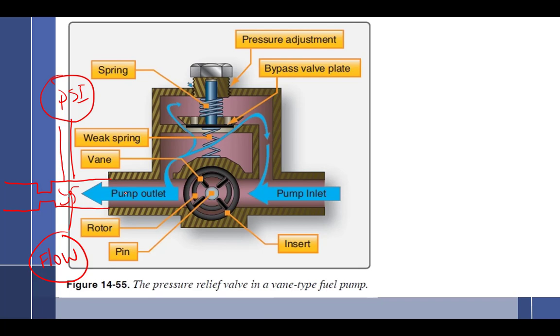Everybody got it? Okay, I'm on the pressure side of the orifice. The orifice is a little bit different. Whatever happens on this side of the orifice depends on what's going on later, so we don't really know about that right now. I set this for this orifice at a certain RPM. Let's say 1,000 RPM. When the pump is moving at 1,000 RPM, it puts out 20 psi, and a flow of, whatever, 10 gallons per minute.